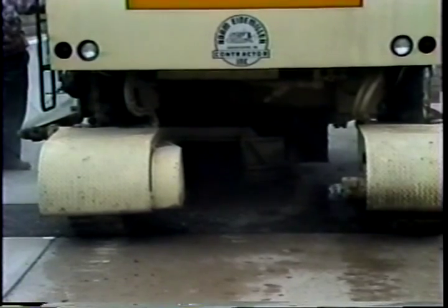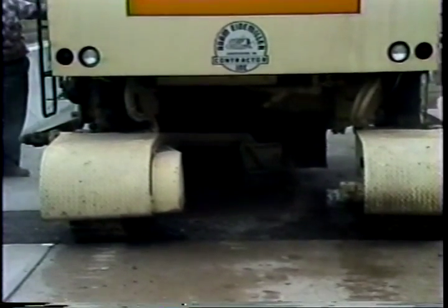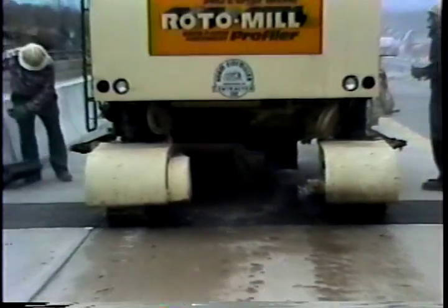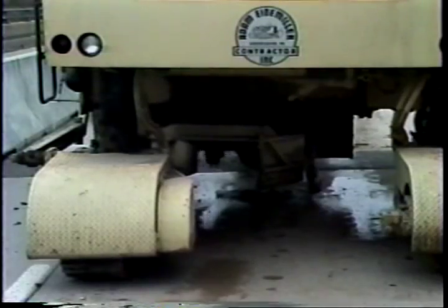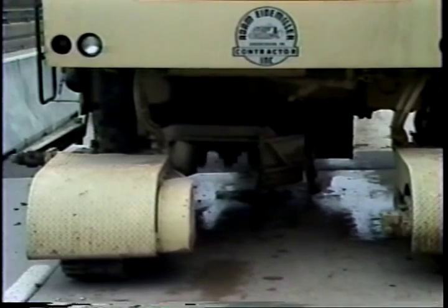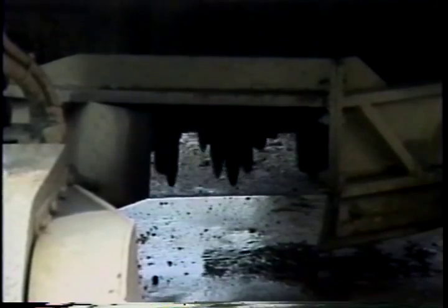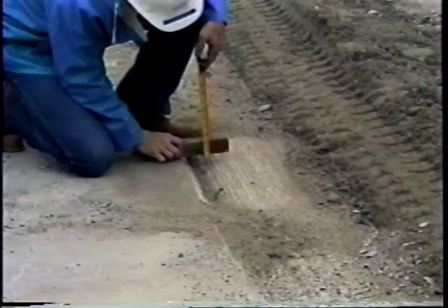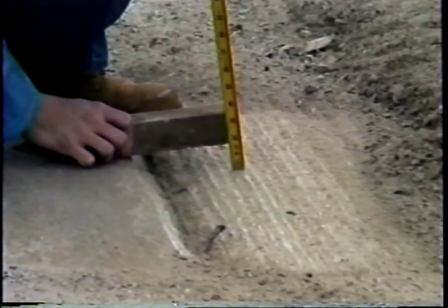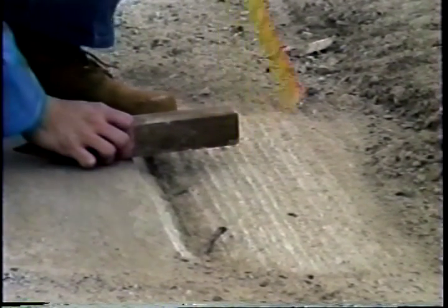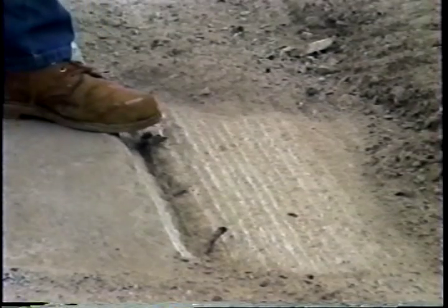Cold milling is especially effective for repairs extending across a major portion of the pavement, such as in full lane width repairs. Carbide-tipped milling machines and diamond blade grinding machines work particularly well because they can be preset to remove material to a specified depth. Although these machines produce non-vertical faces on 2 sides of the repair, they usually don't cause edge spalling commonly associated with feather edging.